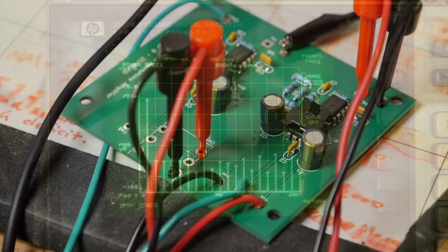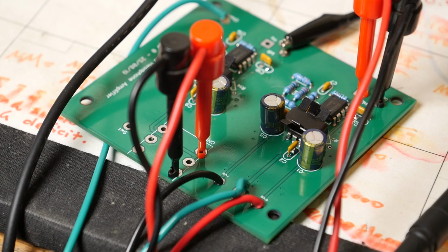Curious. So at the end of all that, what have we learned? It does seem that our error correction circuit is at least helping, because we are seeing some harmonic content there, and we are seeing that if we load the output stage harder, there's more harmonic content in the output of the error amplifier. So that does appear to be working.